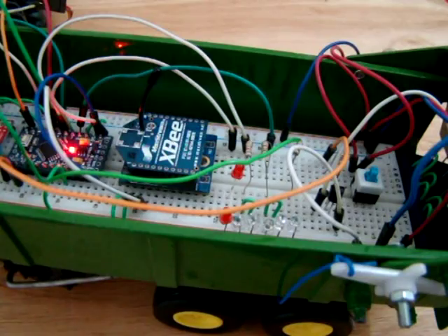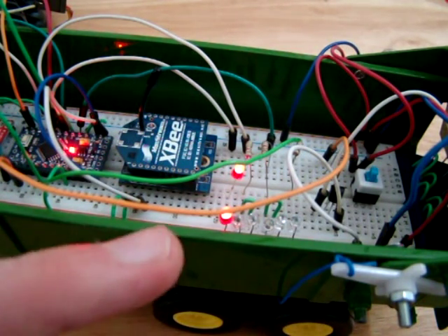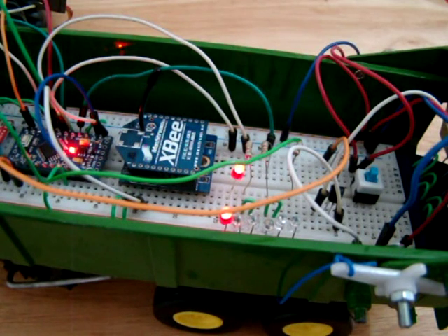So if we go back again and we type in 05 for our dipped lights, so send that. Now we see our brake lights come on when our headlights are on. Now they're actually not at full brightness, they're probably around about half, because I intend to add braking code later on. So basically there will be a kind of speed control, so the tractor won't just instantly follow the analog joystick. It will speed up and it will slow down gradually, and if you pull the joystick back it will slow down faster and the brake lights will come on. That's what I intend to add to the code later on.